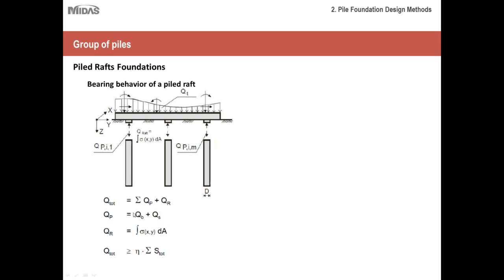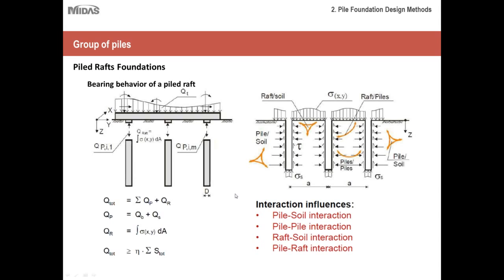So it sounds very simple and straightforward, and it seems like you can just pick up your calculator and start calculating. Well, let me tell you this. You can do that kind of approach, either using PY analysis or hand calculations, for your single pile or group of pile behavior, but not for raft foundations. Let's see why. Here we have this thing called interaction that makes it utmost necessary to incorporate real constitutive material models to represent different types of soil strata and consider the soil structure interaction more deeply.